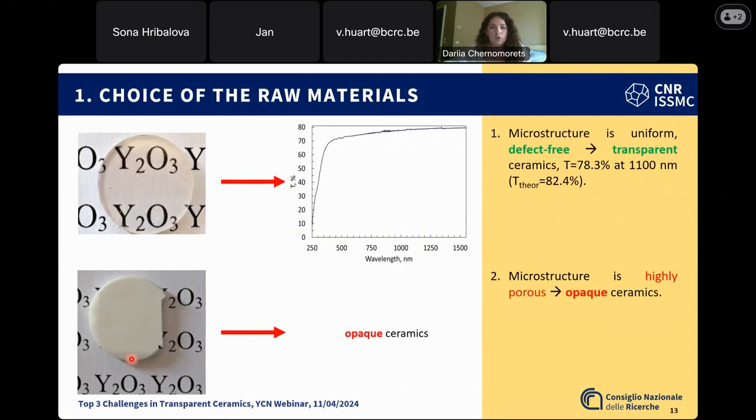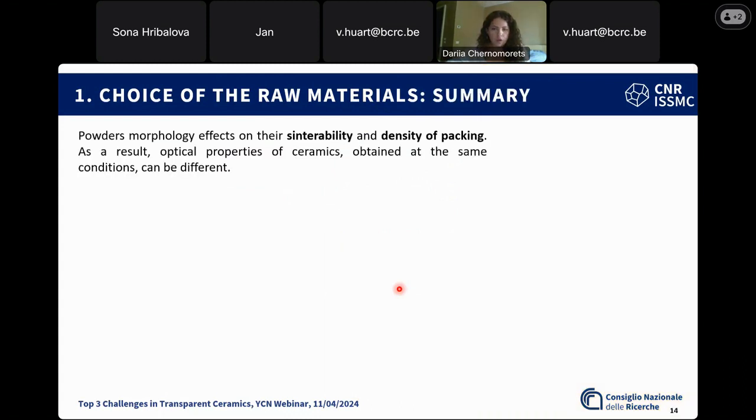So using sintering aids can have some advantages and disadvantages, as with every step. Generally, among the advantages are the possibility to reduce sintering temperature and also reduce grain size. Reducing grain size quite often leads to improvement of mechanical properties due to the Hall-Petch effect. And also promotion of densification is possible.